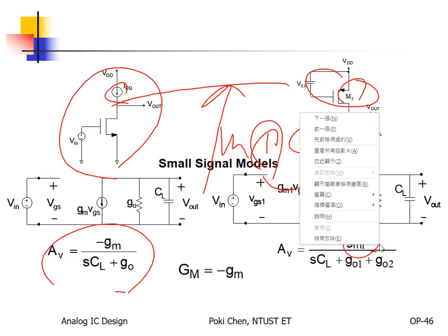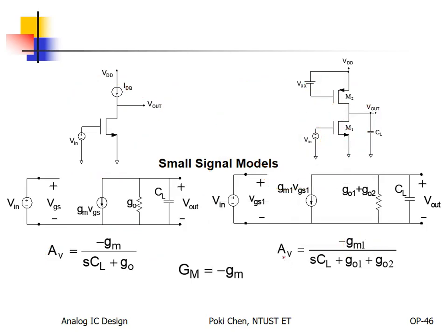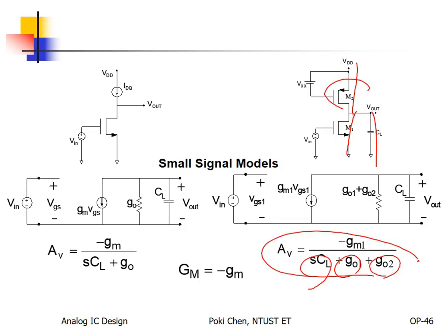But for output conductance, right now you have 3, right? Output conductance here, output conductance. All of them need to be summed up. Okay, so haha, go1, go2, and so on. That's it. You get it. Within seconds, you make it. You don't need such kind of very complicated small signal equivalent model. It simply wastes your time. Okay? Just think. Good enough.